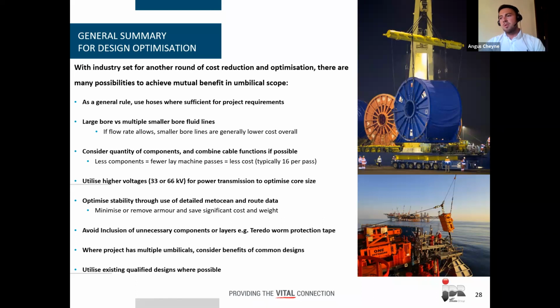Where the project has multiple umbilicals, consider whether you may be able to utilize common designs across that, as that can yield manufacturing efficiency benefits. And finally, look to utilize qualified designs wherever possible. Although there may be some benefit in performing project-specific testing, we certainly wouldn't advise performing full-scale requalification unless there's a significant design change or it's pushing the boundaries of existing technology.